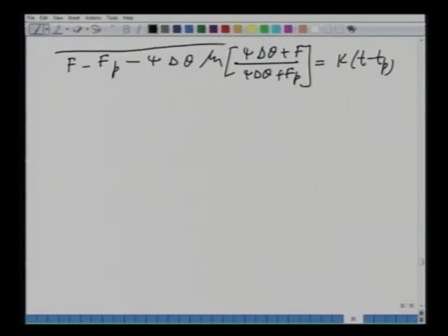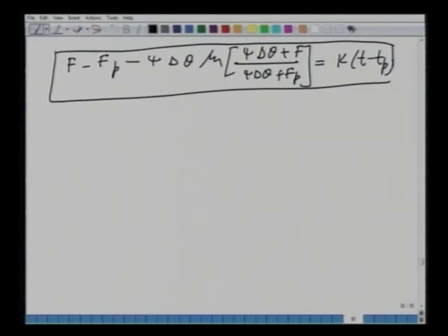This is your final form of the Green-Ampt equation, which can be used after ponding. Let me number this as 18. Equation 18 gives you the infiltration F at any time after ponding. It involves Fp, which is nothing but I times Tp.